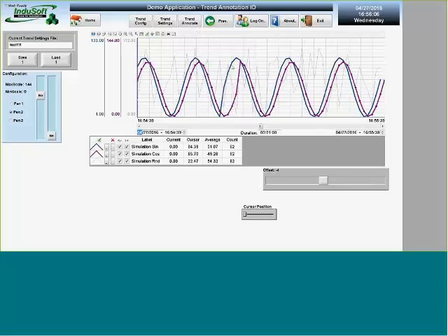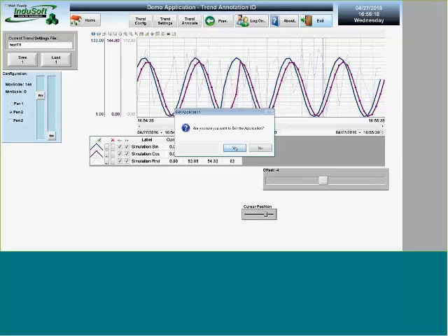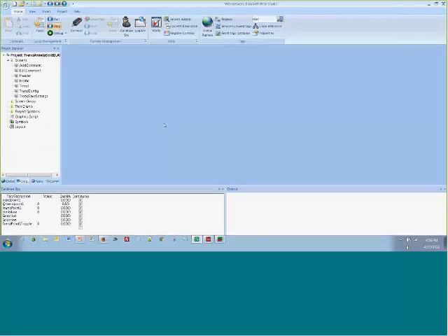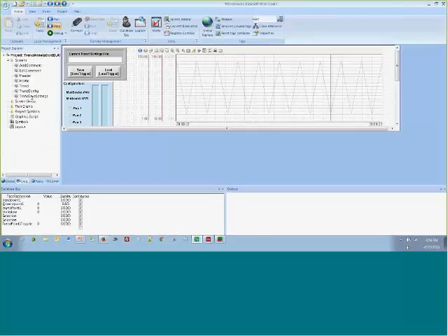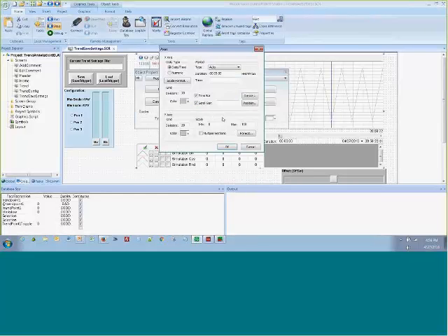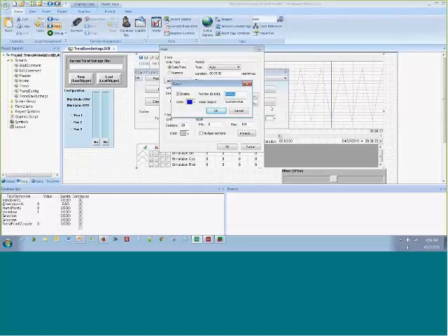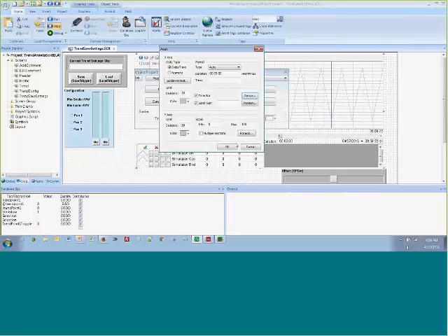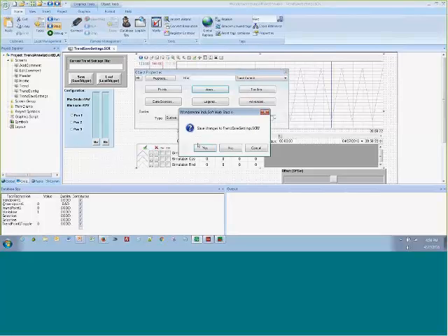The other thing is you have this cursor that you can click. Most people know that you can click on the screen, but a lot of people don't know that you can actually move the cursor with a tag value. So here I can move it from 0 to 100%, and where that's done is here in your axes under cursor. So I set a cursor position 0 to 100%, and I can slide that back and forth and get the result value into a different tag. So that's one way that you can do it. Now, good eye, whoever sent that in, that we can use indirect tags.